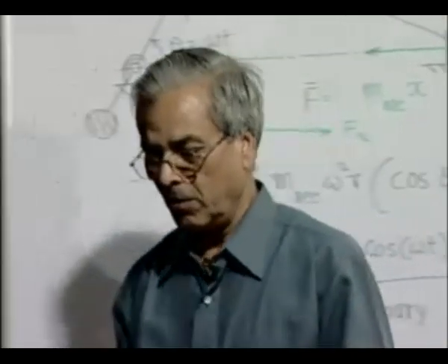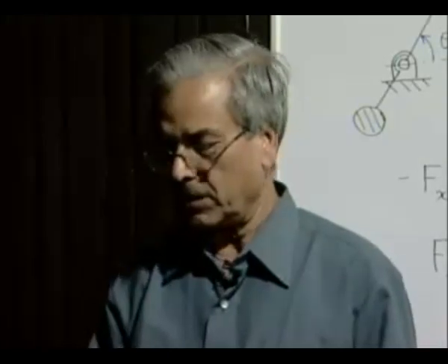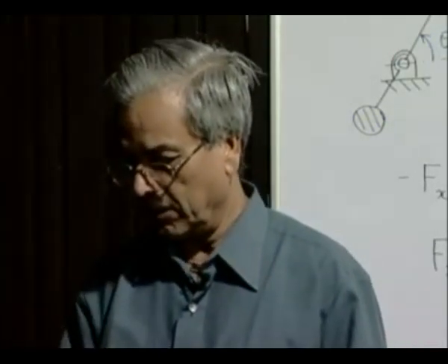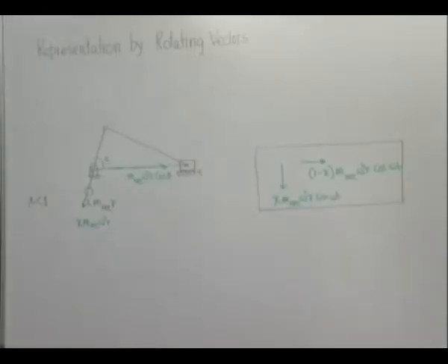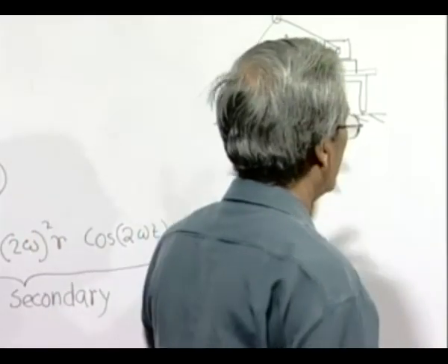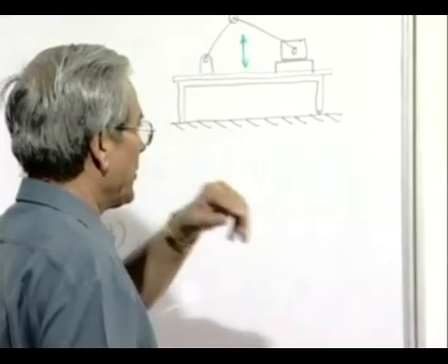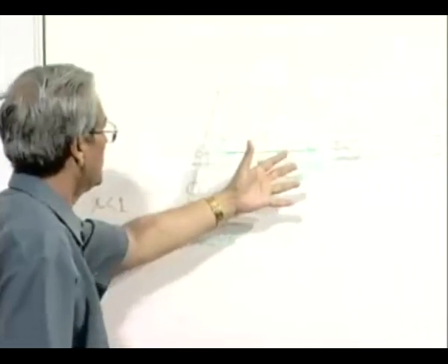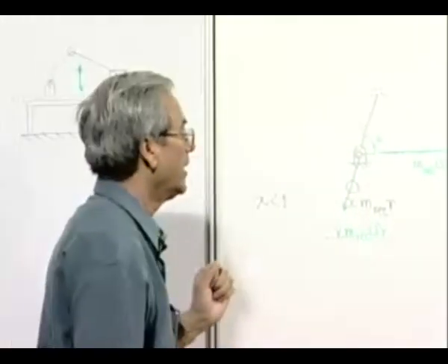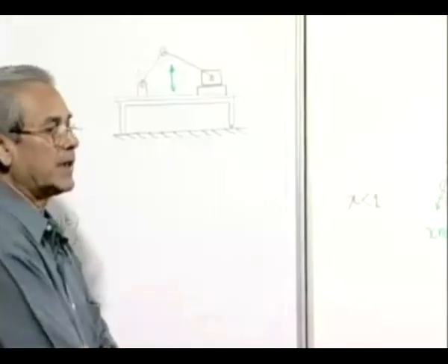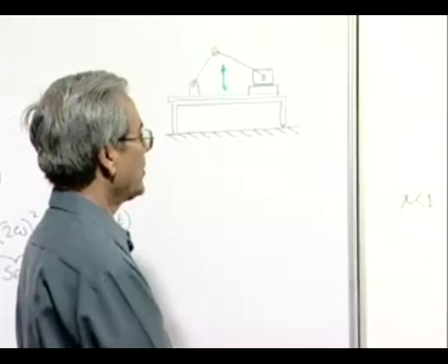However, you can also stretch your imagination and consider a complete balancing of the unbalanced force. Now, if we have to do complete balancing, then obviously you have to keep two things in mind: that you have to neutralize the force without generating a force, as we have done in this case by adding a simple counterweight.